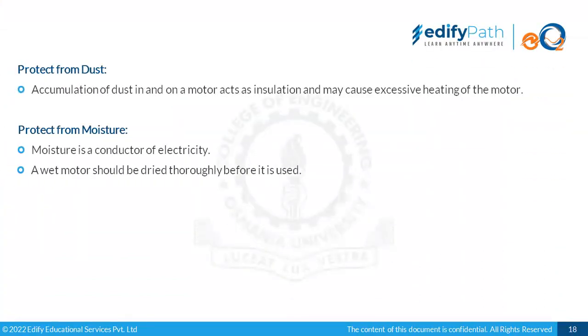Protection from dust. Accumulation of dust in and on the motor acts as insulation and may cause excessive heating of the motor. As we said, motors are all-season components, so they could be installed anywhere depending upon the process. There could be heavy heat generated near it, or there could be a process where a lot of dust is being generated.